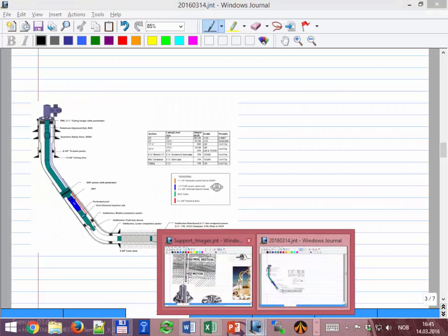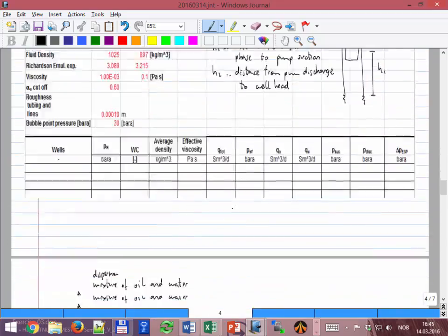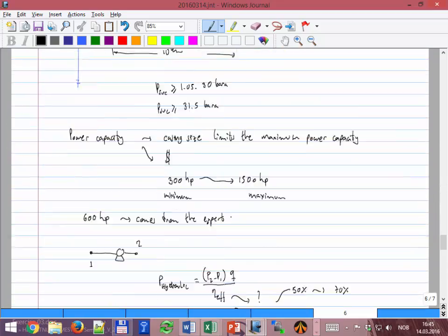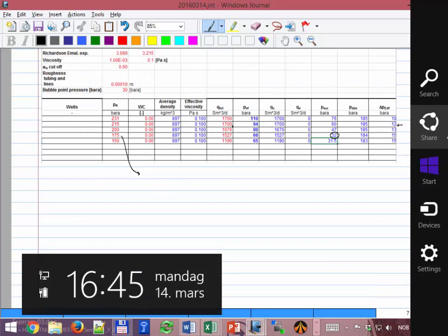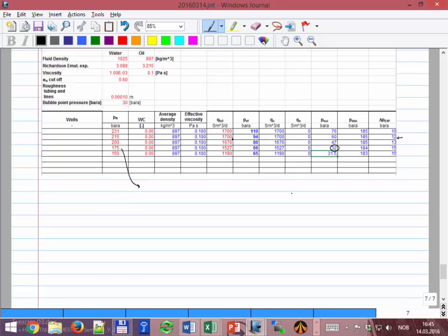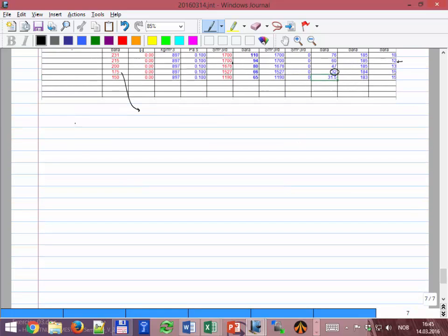Okay, now let's go back to pump theory, and let's see how, with this very rough analysis, we can do a better analysis if we already have a pump. So I told you last class how the pump behaves. What is the delta P of the pump versus rate? Looks like an IPR going down. And this rate, remember, is the local rate, total liquid rate.